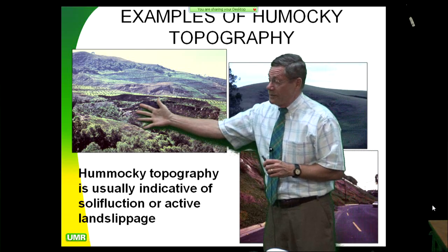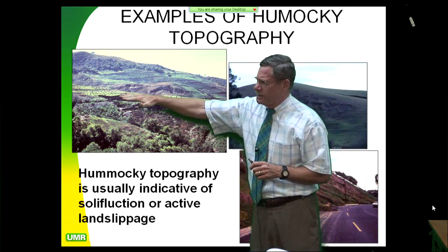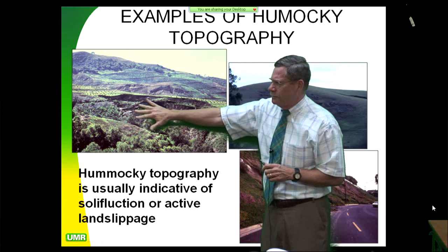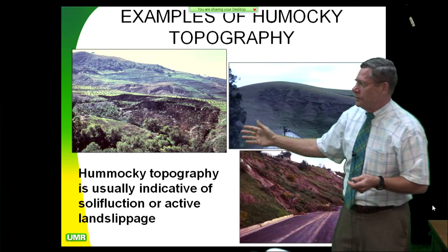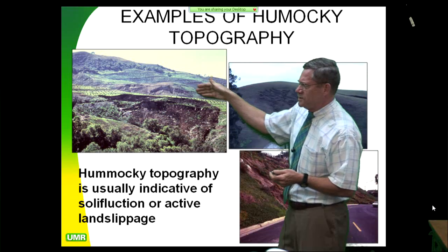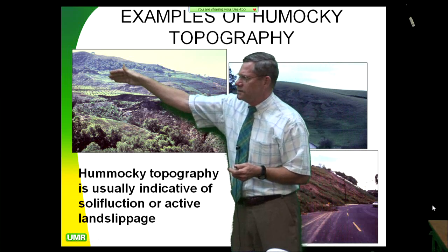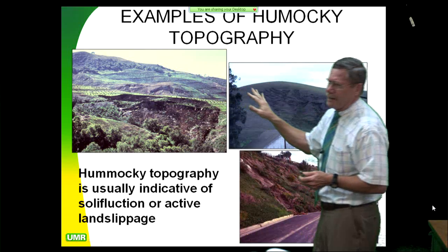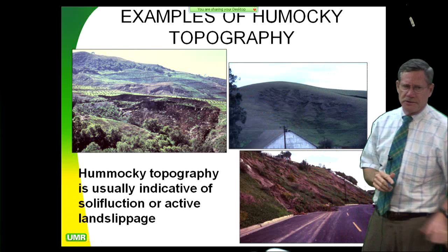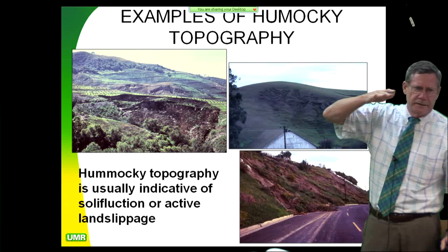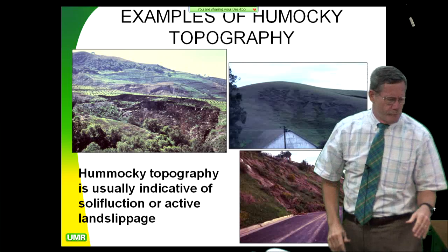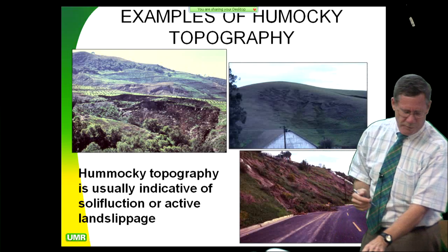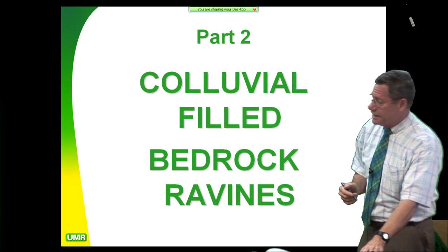So what happens here is this got sufficient moisture that the whole mountain just started coming apart and moving. And when you look back on the aerial photographs, what you see is gigantic hummocky structure up and down this entire valley. That's all structurally controlled by that blind thrusting coming up, because the blind thrust perches the groundwater. Blind thrusts are very, very problematic with large slides.